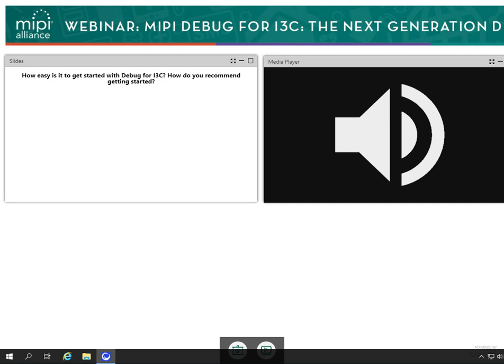It's called the Simple Address Map, or SAM controller. So there are some very, very simple controllers that can get you started doing very simple peeks and pokes and things like that from a debug perspective, which is probably done very easily in an FPGA to play with and get familiar with. And then build up, depending on what you need, into those sneak peek engines, where you can get way more fully featured capabilities.